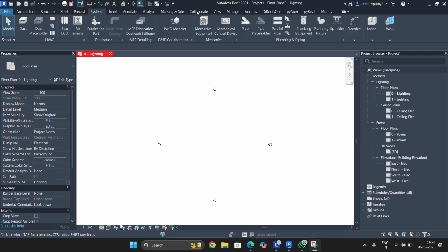So in the past we have covered how to make a central file, the Revit interface, and how you can link a Revit file into your model, how to copy monitor grids and levels, and what is a workset and how you can make a workset.